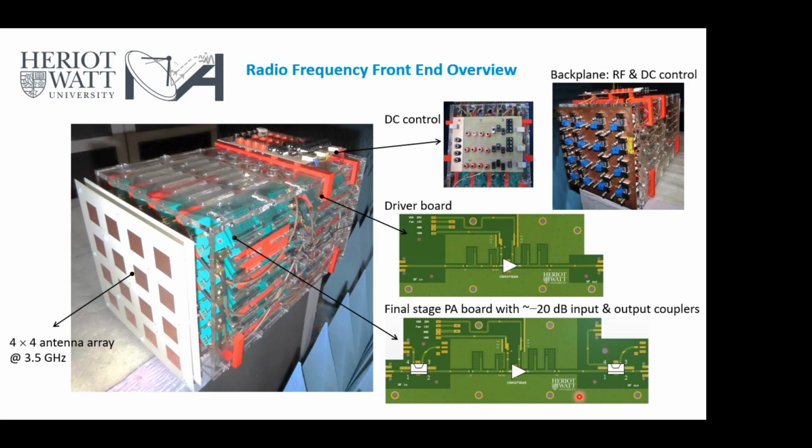And that design is actually also what Aymeric used in his simulation, and this is a fabricated board. The driver and the PA share exactly the same design. Behind these PA boards at the back, we have the backplane, that's related to each cell. So for each chain, we have the input port and 2 ports to observe the 2 couplers, and we also have the DC control to give the bias to the 2 PA boards. Also, we have the DC control to the fan. And here is another extra PC control to directly connect to the power supply.